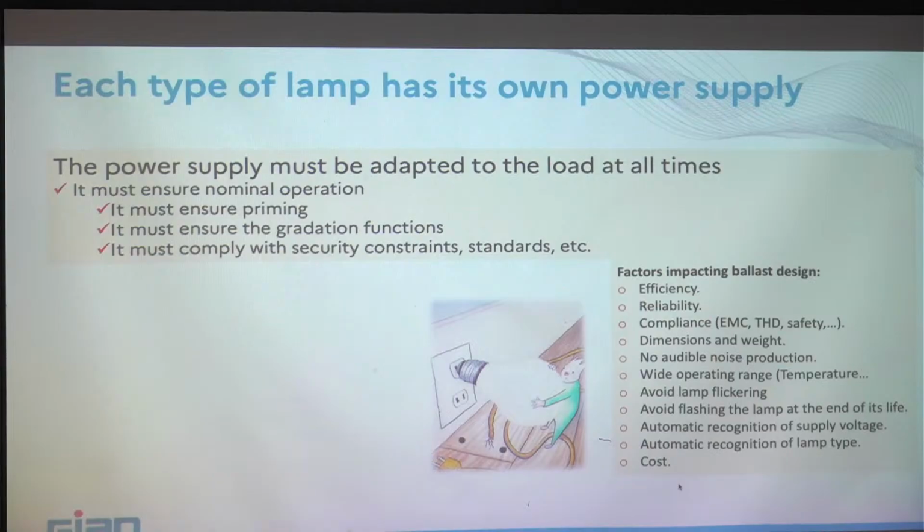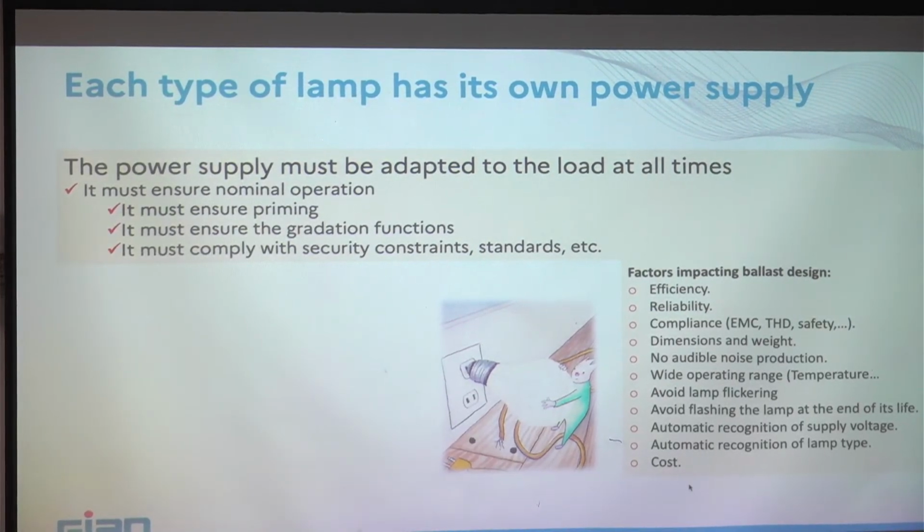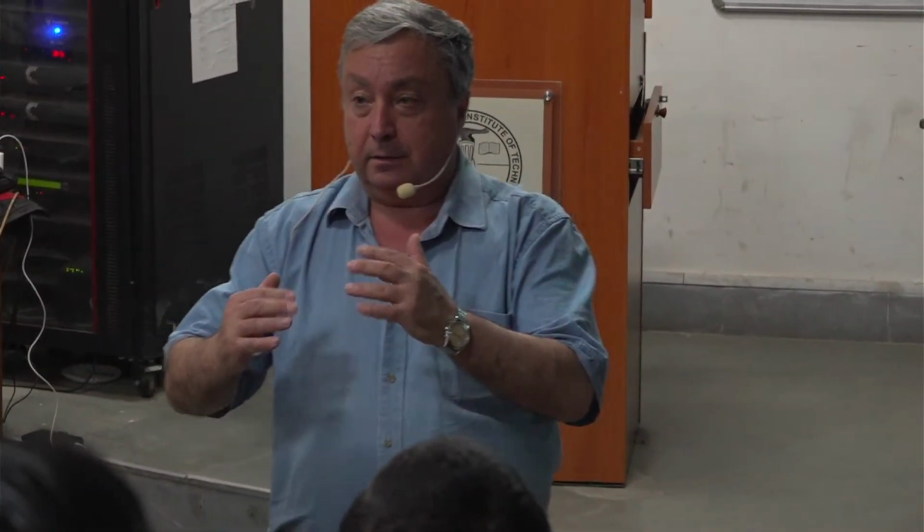Some of the fixtures can accept different kinds of lamps. It was the case with T8 and T12 tubes. We can replace some T5 tubes with LED tubes. It will be nice if we have a driver that is able to know what is behind and adapt the driver characteristics to the load.